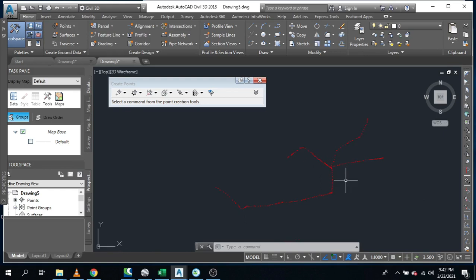After this, we need to know the total number of our coordinates. For me, the total number is 225, but it depends on your points. Now, we need to make sure that our coordinates are linked by lines. As you can see here, they are not linked. We need to make sure that all of our coordinates are linked by lines, and these lines between the points are going to act as water pipes in EPANET. So that is very important.